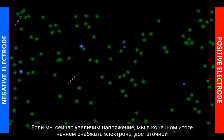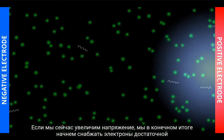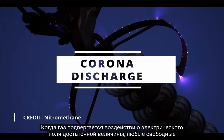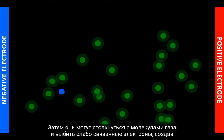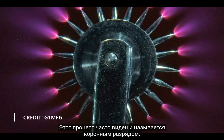If we now increase the voltage, we will eventually start to provide the electrons with sufficient energy to initiate a corona discharge. When a gas is exposed to an electric field of sufficient magnitude, any free electrons will accelerate under its influence. These may then collide with the gas molecules and dislodge weakly bound electrons, producing a free electron and a positive gas-ion pair. This process is often visible and is called corona discharge.